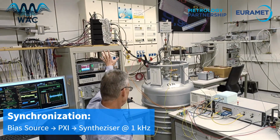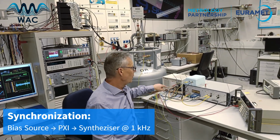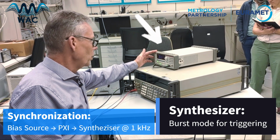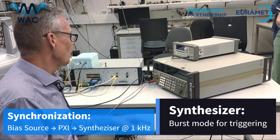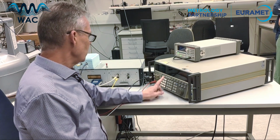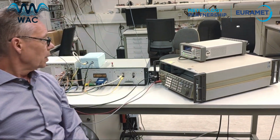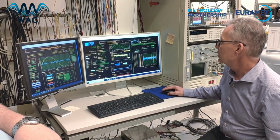The bias source is sending the clock and the trigger signal to the PXI, so the PXI is synchronized, and then it's forwarded to this little synthesizer here, which is in the burst mode and gives the proper triggering to the calibrator. So I also have to put this to 1 kilohertz. It's in the burst mode, so I can operate this instrument and have to go on phase lock. Yes. Push the trigger once, and then I should see the differential signal here.